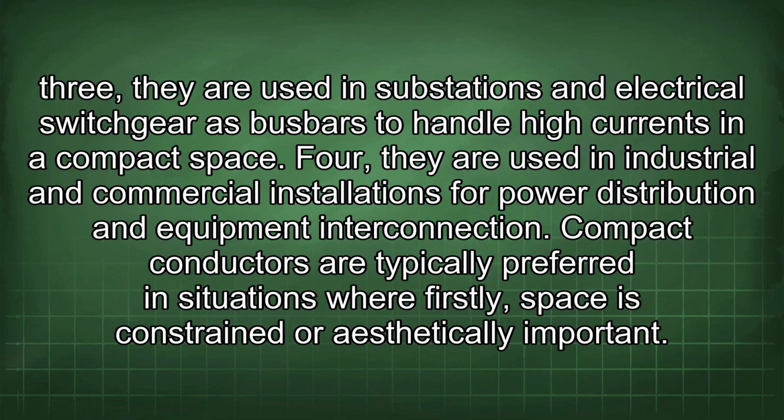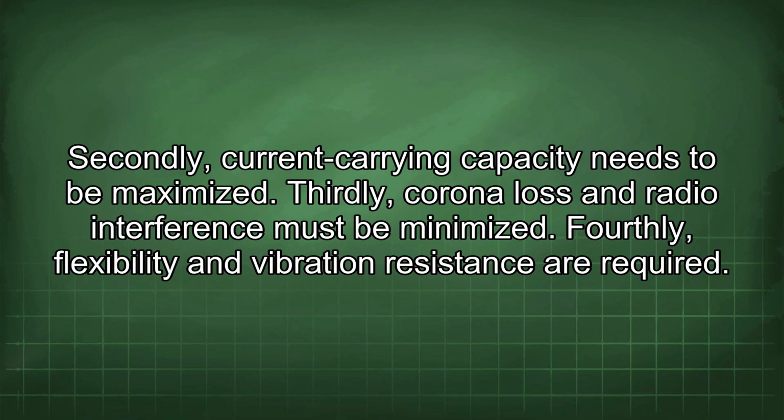Compact conductors are typically preferred in situations where firstly space is constrained or aesthetically important. Secondly, current carrying capacity needs to be maximized. Thirdly, corona loss and radio interference must be minimized. Fourthly, flexibility and vibration resistance are required.